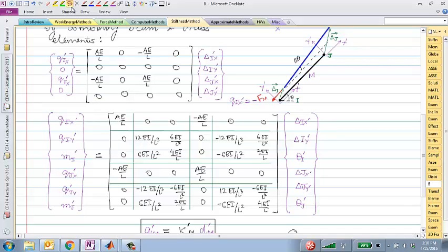So let's consider this beam element in the horizontal direction. So global and local systems are exactly the same. Now, if I were to extend it by some amount, and after extending it, maybe take one of those ends, one of those nodes, say node I, down by some amount, while keeping everything else exactly the same, would the transverse force, these transverse force and moments required, would they depend upon the amount of extension that I've done?